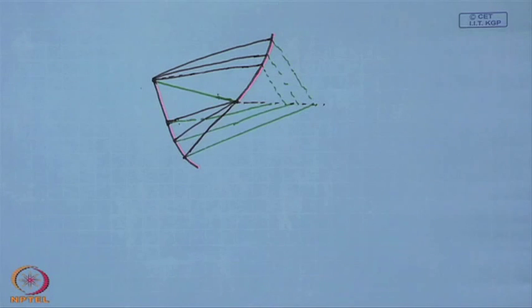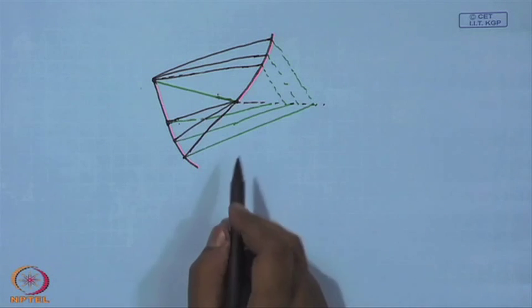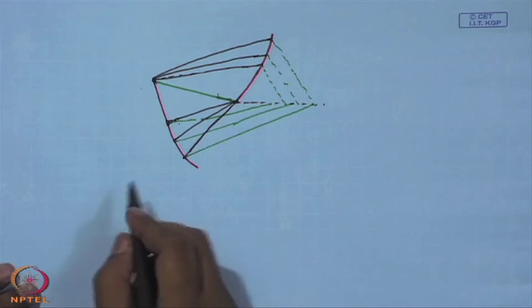We have seen that in subsonic two dimensional inviscid flow there is no drag force. The drag force in inviscid flow can come only in 3 dimensions, which is lift induced drag. However, in case of a supersonic flow we see that there is a drag in 2 dimensional inviscid flow as well. This drag is known as the wave drag.